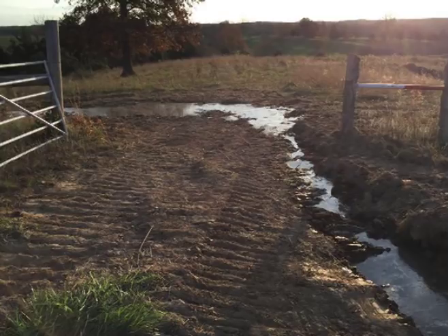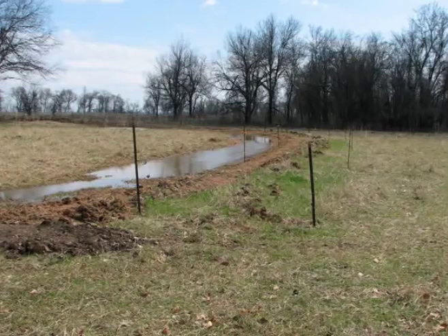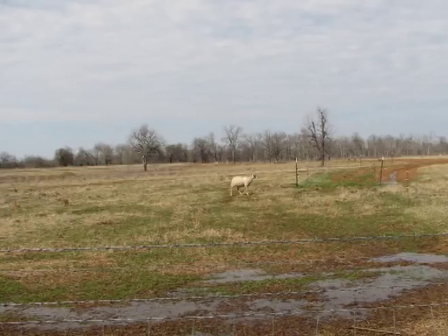So the water goes from here, through a channel, out to the ridge, and then sheets off the ridge. So now we have moister ridges. You can have an end outlet, because if you take water that's a foot deep and a foot wide, you split it in half, it's now a half foot by a foot wide, and then you stretch it out over half a mile. How much water do you think is coming out the end? Hardly any at all. So once you get out to the shoulders, the water has been stretched out so thin and had time to soak in that you don't have a big gully washer going down the middle of it.